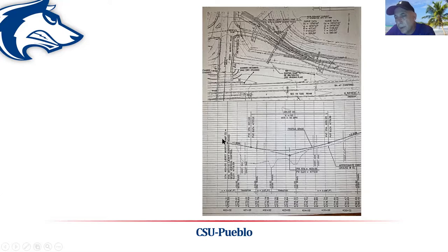Actually, this particular curve process starts because stationing increases from the left to the right here. It actually starts over at the overpass and actually transitions down as it goes back onto the highway system. So this is a good example of a vertical curve. This is found in your plan view. Here you find the horizontal curve information. In the profile view, you find the vertical curve information.